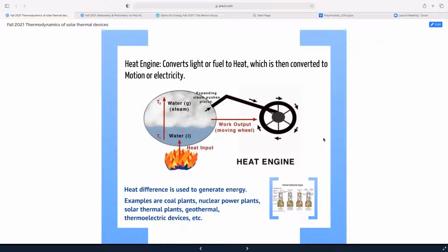So, of course, more than 100 years ago, the steam engine is a good way to think about this. You have a hot region where you are inputting the heat that converts the water into steam, and the steam essentially performs the work on the piston to push the wheel. And of course, it cools as it does the work. Why does it cool? Because the steam expands, the pressure drops, along the pressure-volume curve the temperature cools, and it condenses, becomes water again, then heats up again. So that's the cycle, and work is done.